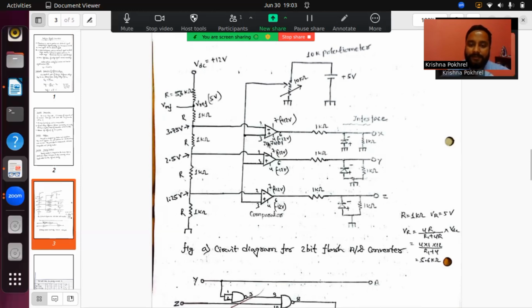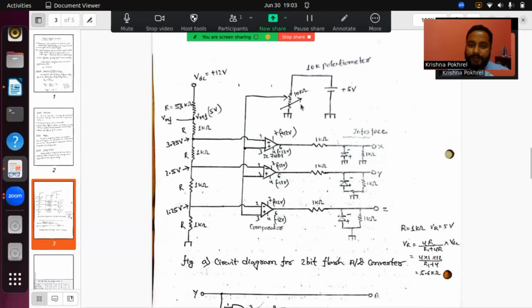We will connect each and every op-amp. We need 3 op-amps, and we will connect the 3 number terminal of each op-amp and take it outside, and we'll connect one potentiometer here. Now this potentiometer is 10 kilo ohm. A potentiometer is a type of resistance which helps to change the value of resistance and get our voltage, because a 5 volt power supply is connected to the potentiometer, and the potentiometer gives an output here by dividing some voltage. We can increase or decrease this one.